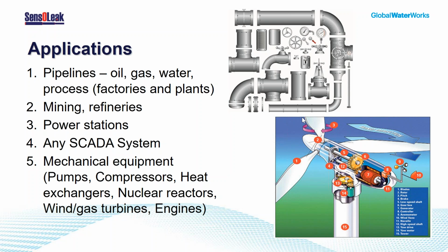Sometimes we recommend that operators install additional hardware, maybe acoustic sensors or some other sort of sensors in specific areas, sensitive areas, politically sensitive, or residential areas, or close to water areas, especially in oil, because the damages are basically enormous when there's an oil spill next to a water source. And it's applicable to anything in the systems, not just the pipelines, but the pumps, and we provide also alerts about the sensors. We monitor everything.